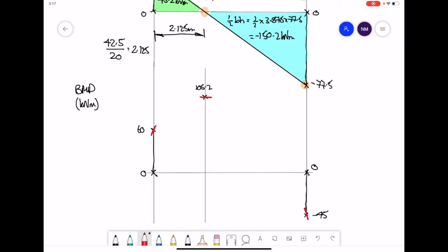And what we have to do is to draw in a line of some description that will join those 3 tangents in one go. How you do that is you essentially draw on a curve that follows those tangents. To do that, you would start off with a positive gradient, coming to a maximum value. Then from that crossover point we would continue on all the way down until we come to the very end. And that is your bend moment diagram for member BC.